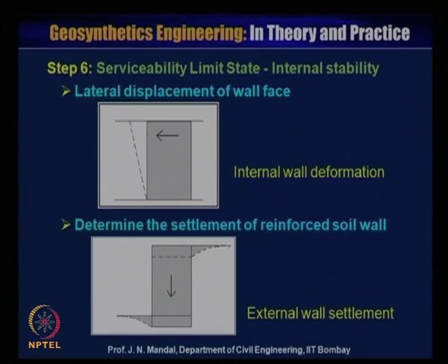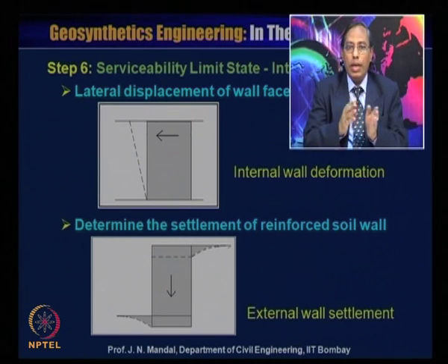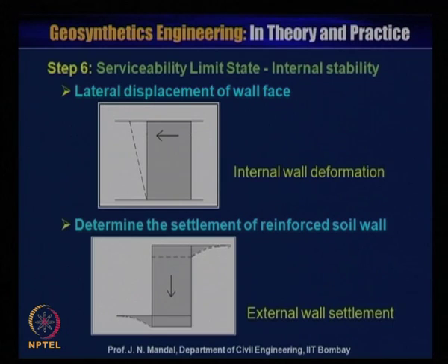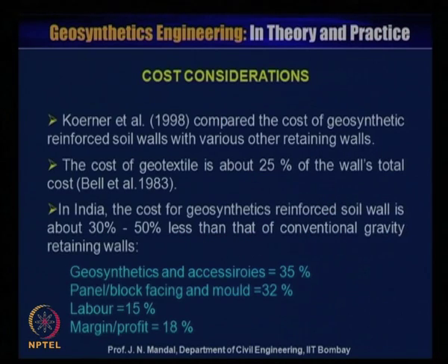Step 6, serviceability limit state for internal stability. So, there is a possibility for lateral displacement of the wall face. So, you have to check what will be the internal wall deformation, or you have to determine what will be the settlement of the reinforced soil wall for external wall settlement. So, these are the serviceability limits for the internal stability that have to be checked.